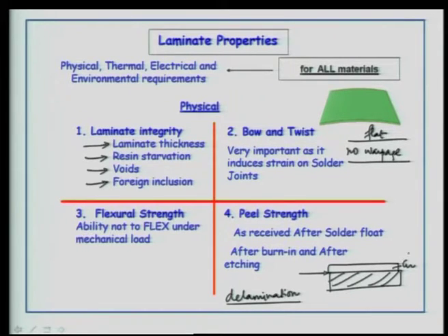Now, this is the core. The core should not exhibit any delamination. How do you test that? In the manufacturing of the copper clad laminate, basically they take samples of this laminate and then allow it to float on molten solder. Okay.